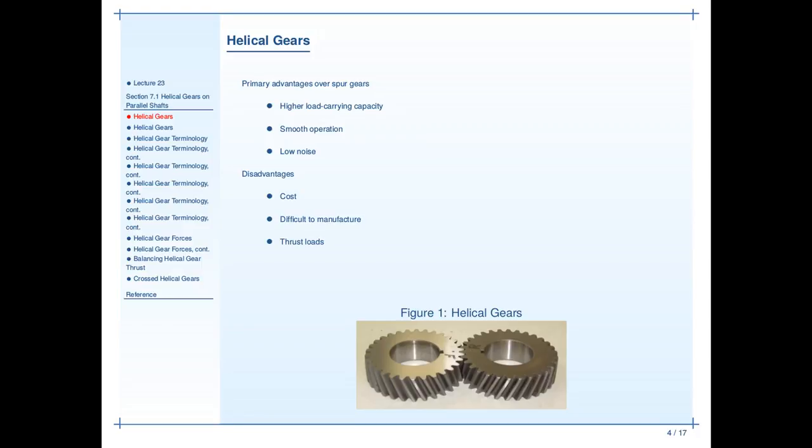In addition, spur gears, at least in most circumstances, have a very low thrust load. That means that you only get a tangential force and a radial force with paired spur gears. Helical gears, on the other hand, create a thrust load. That means that you must have something to react against them in the axial direction, or they will move.